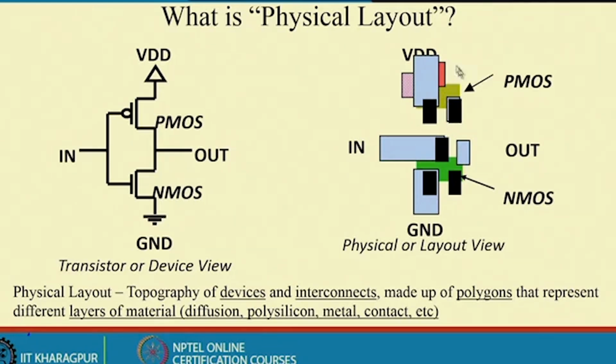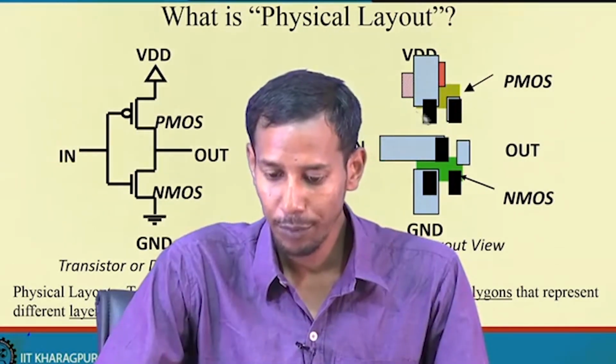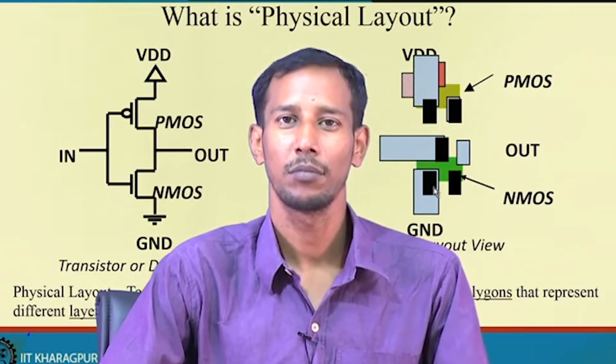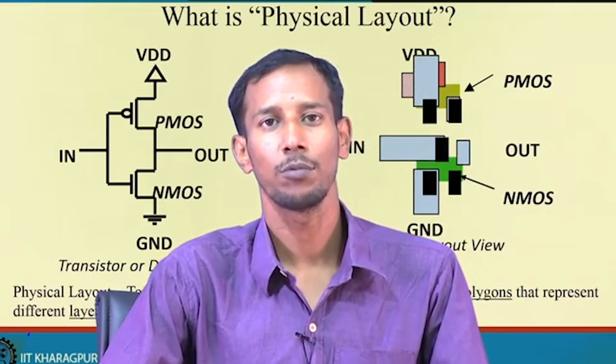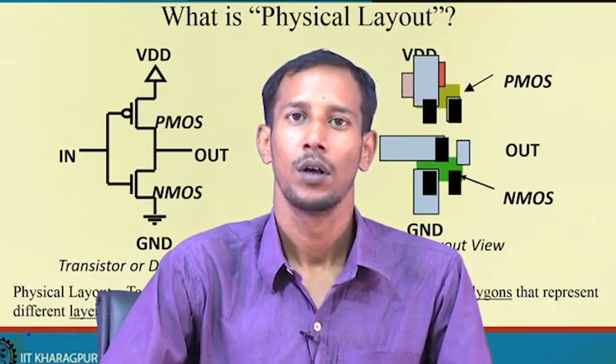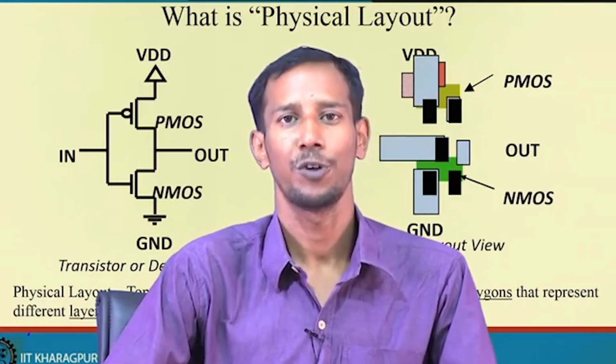Here, this part is related to PMOS and this part is related to NMOS, then there is a connection common between the gates, and for the output there is a common source, and from there comes the output. This information for PMOS and NMOS is provided by the technology library which you are using. This will be different for different vendors.